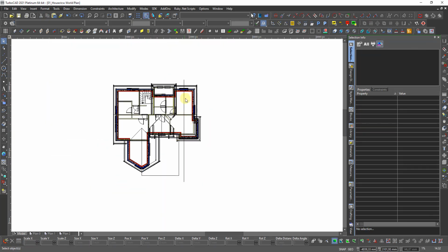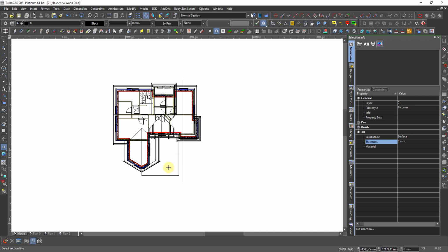Then we can make a section out of this, a vertical, and then I select the section line, this one. It's only 1 millimeter, I don't know why I wrote that. And then I select the 3D entity, and I want everything. I click, release, and then drag over and click again.